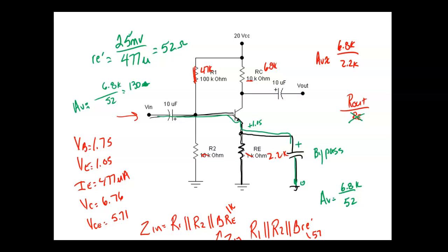What resistor in there keeps the beta from changing with temperature? So we actually looked this up. I hooked up a little switch, I put it in the middle, I brought a soldering iron up to it, and the voltage dropped across the transistor started going down, right? So as soon as we set this right here to 1.05 volts DC, beta can't change anymore. Because if beta tried to go up, this resistor right here would try to drop more voltage, but it can't because it said it was 1.05. If it tried to go down, this guy here would drop less voltage, and the transistor would automatically turn on more, right? You understand that?